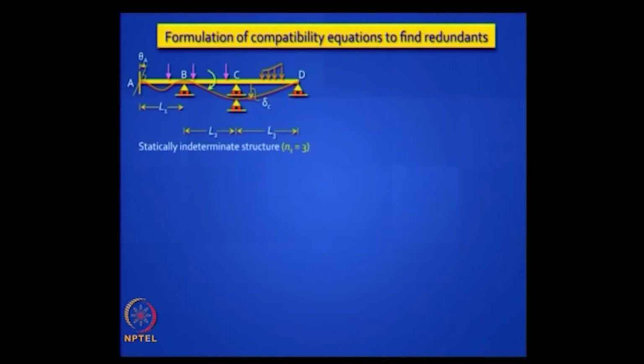So you have many choices of the primary structure. Which one would you prefer? Cantilever, it is easiest to draw. So good. So you remove all those 3 supports and you can basically identify the reactions as x1, x2, x3. Now one would imagine those reactions will be pointing upward, but there is a good reason to assume them to be pointing downward for calculation purpose. I will show you the reason in a while, and then they turn out to be negative, which is totally acceptable.